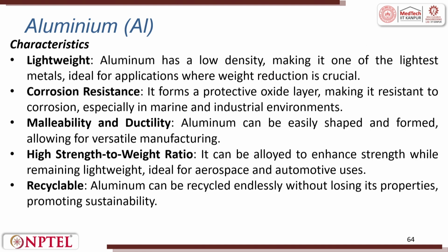So, aluminum has multiple properties, and these properties are common for almost all the non-ferrous alloys. Lightweight, except for certain ones, for example, lead alloys are heavy, but apart from that they are all lightweight. Aluminum has low density, making it one of the lightest materials. Corrosion resistance, because it quickly forms an oxide layer on top which protects it from corrosion. Malleable and ductile, it can be given a shape and drawn into a wire. High strength to weight ratio: because it is lightweight, whatever strength we have is very high. Then it is recyclable.